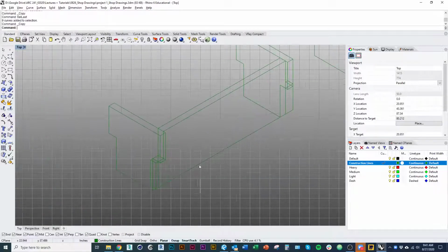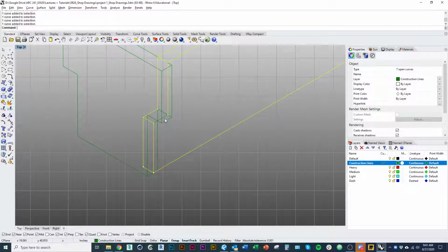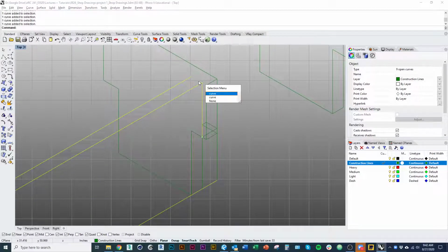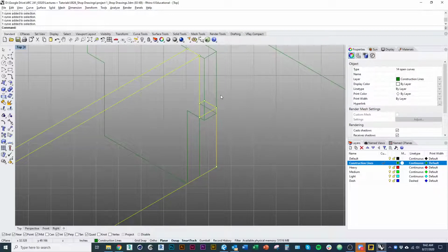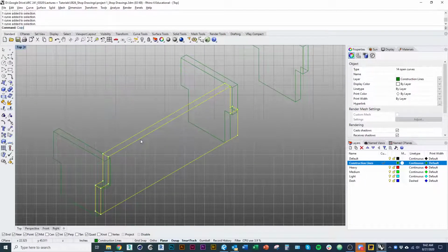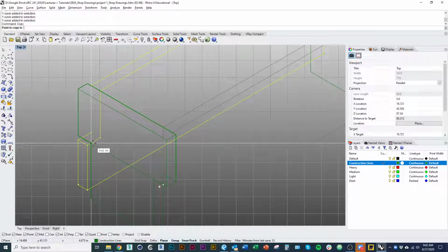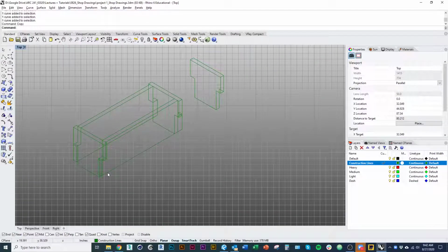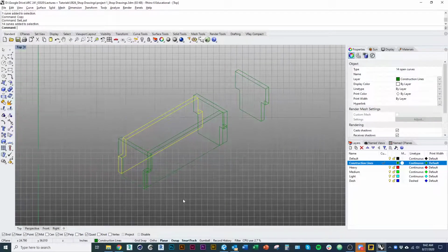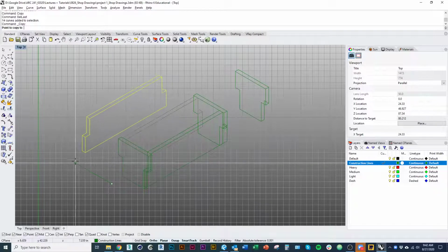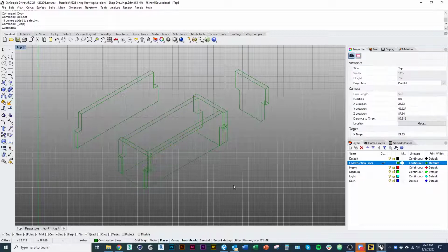And I'm going to do the same with the long side here. Going to copy it. You would see that over to there. And again, I'll type in select SEL last, and we'll copy it off to the side. And I'm moving it just far enough away that we'd be able to see the whole thing separate from the original drawing.